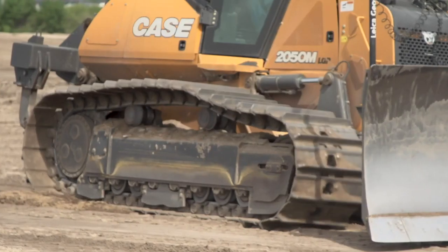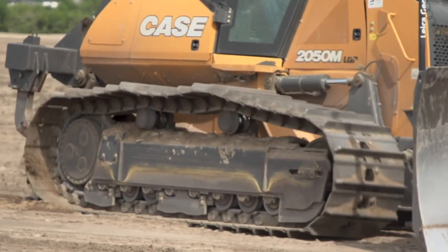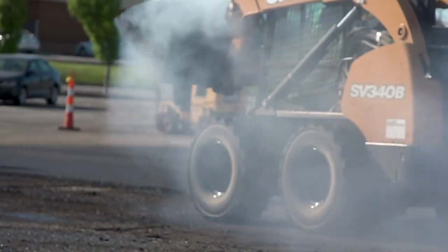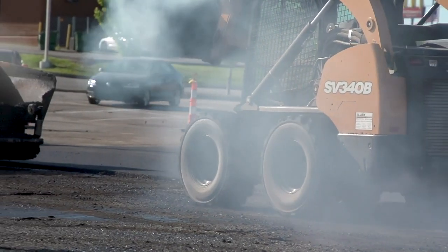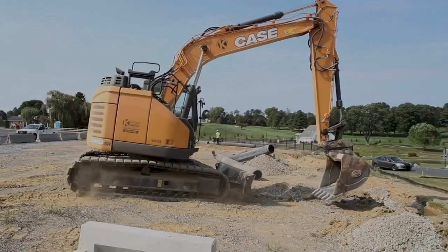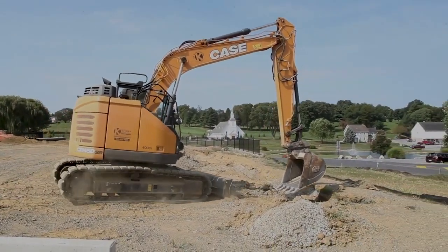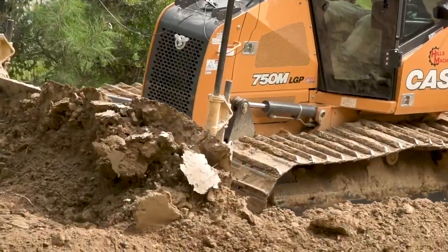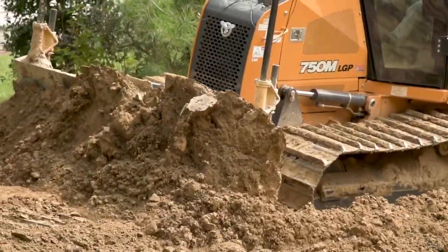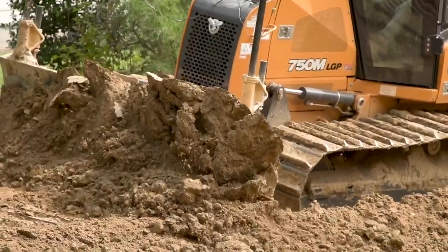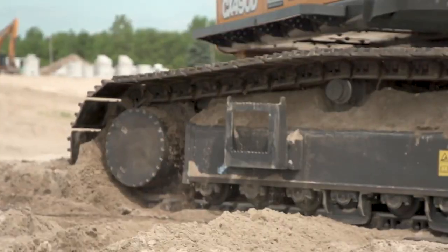When you look at tracks and tires, probably the best suggestion that I can make is to get yourself or your crew into a routine of doing a daily walk around of the machine, a pre-operation inspection, to ensure that that machine is ready to run. This inspection gives you a constant reminder of what the machine looks like, any new dents, dings, or scratches, and gives you the ability to understand what's changed on the machine from the last time I operated.